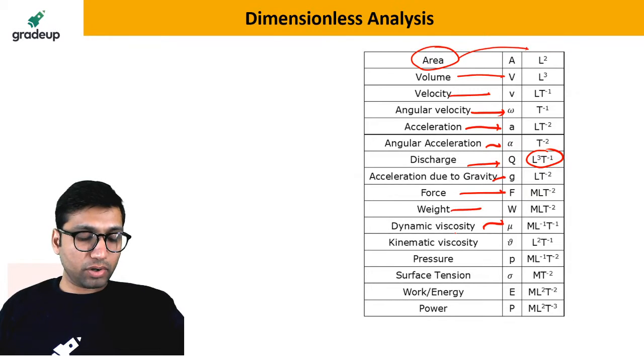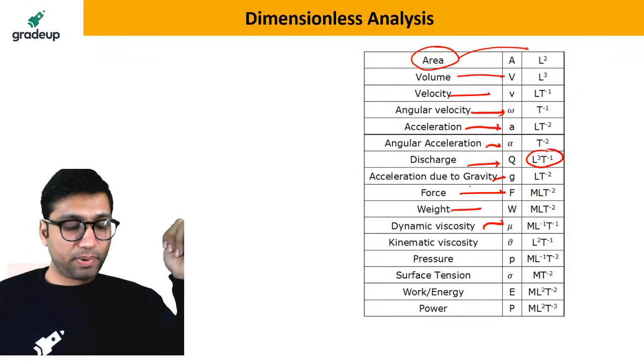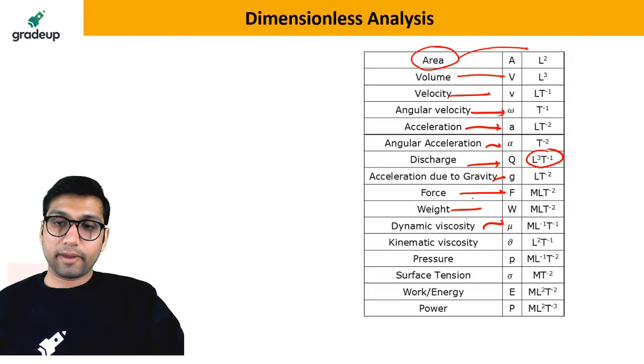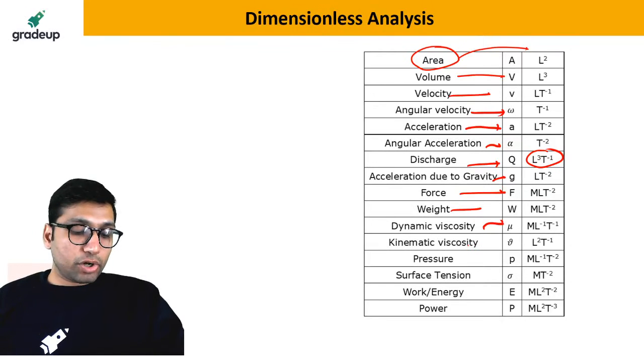Velocity gradient is not 0, Shivani, velocity gradient is negative. When pressure gradient becomes positive, velocity gradient becomes negative. Okay, that is the condition of flow separation.